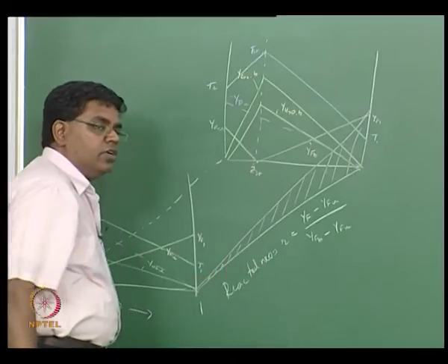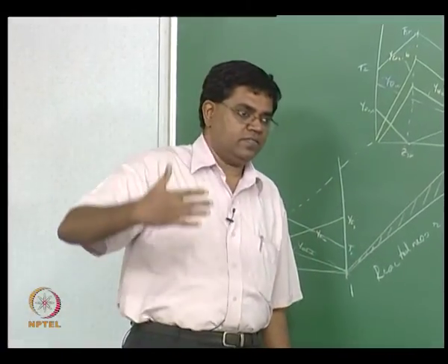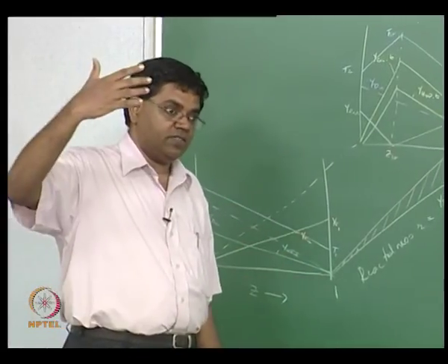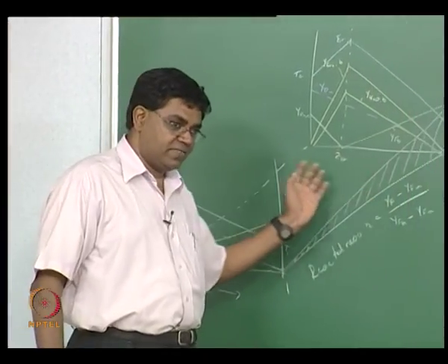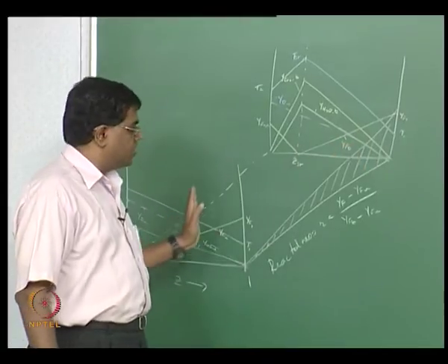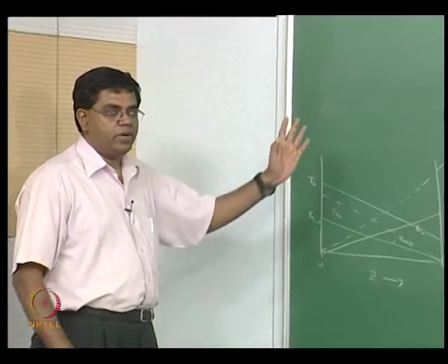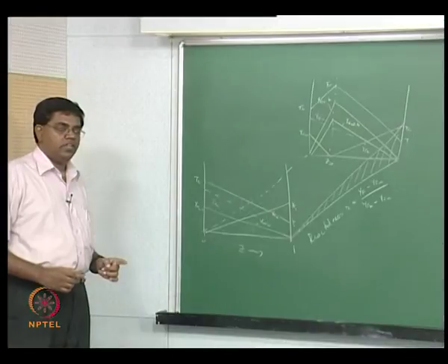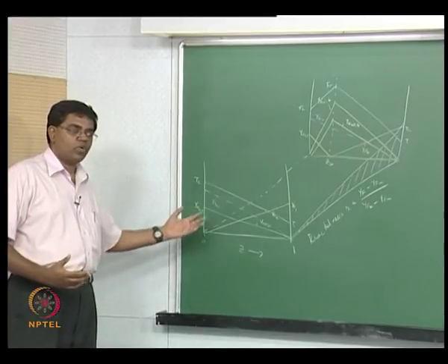But in the flame we are looking at how it is behaving in the mixture fraction space rather than in the physical space above the burner. So in this picture everything looks very nice, straight lines, all linear dependences in the mixture fraction space, but that's not how the curves were looking in the physical space, and that's one of the reasons why the mixture fraction space is quite valuable.